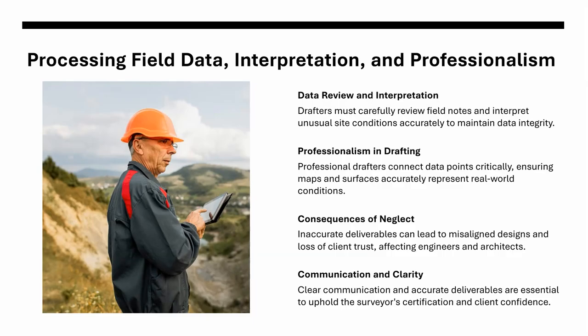If deliverables are not prepared correctly, if the CAD file does not match the plotted sheet, if the vertical datum is inconsistent or erroneous, if our coordinate system is just flat wrong, the engineer or architect may discover far too late that designs are misaligned. And this is why communication with the client and clarity in deliverables are every bit as important as the field data itself. And I will repeat the guiding line one more time for y'all.